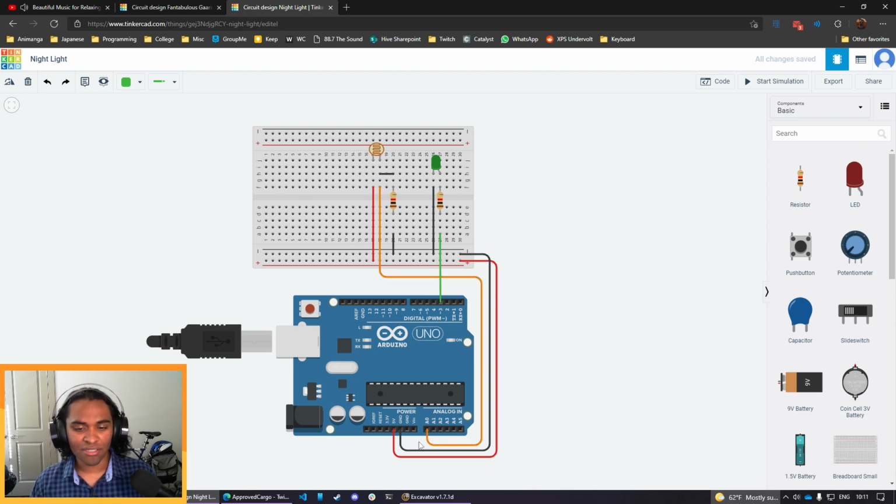And so it's not practical to convert those values directly into code, because when you're coding something, you have to use specific values, right? And unfortunately, converting a continuous scale to a discrete scale does remove some resolution. So say I had one signal that was 2.0000 volts, and then I had one that was 2.00001 volts, or something like that.